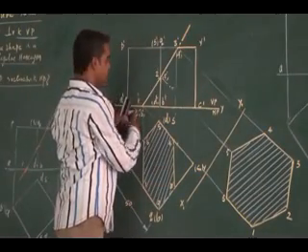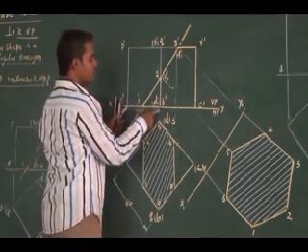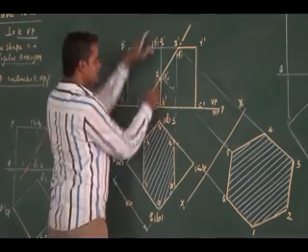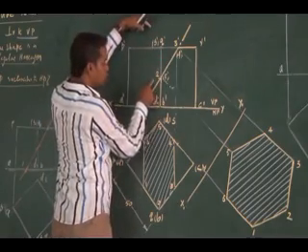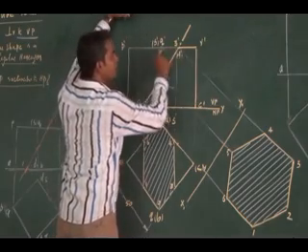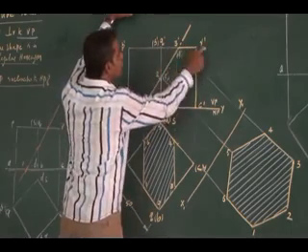So I can represent the cutting points in an order. This is my cutting point 1, cutting the visible edge AB, and it goes along the cutting plane, it cuts the visible vertical edge, that is BQ. That's the cutting point 2. Then you go along the cutting plane, it cuts the visible face edge, that is QR.